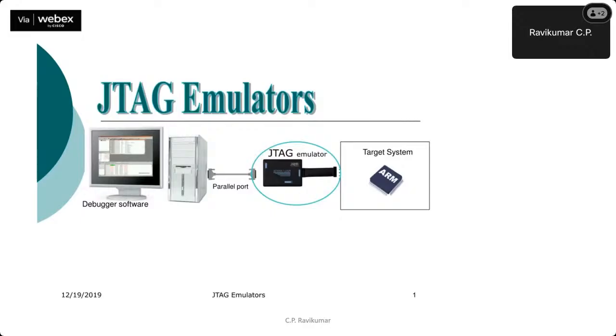You may want to put a breakpoint and read out the contents of the register and display them here, and things like that. So JTAG is very useful here also, right? Because it has ways to shift instructions into your processor boundary scan of the processor, and that instruction could be something like, I want to know the content of a particular register, right?